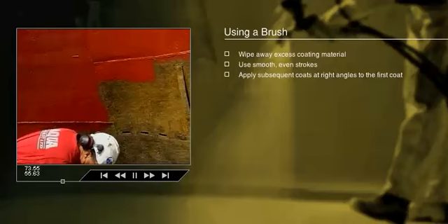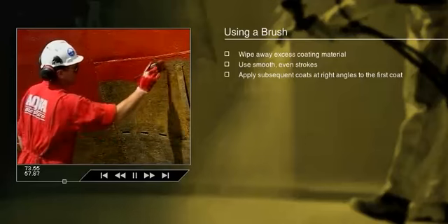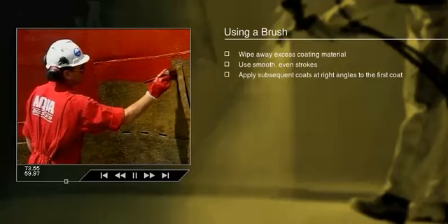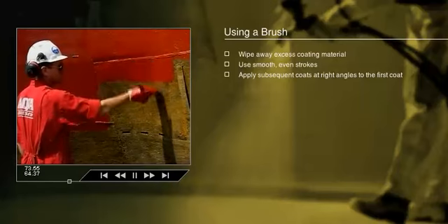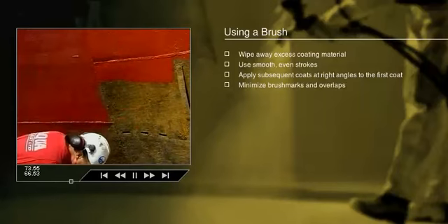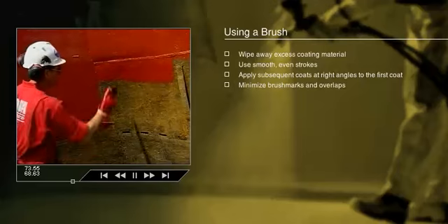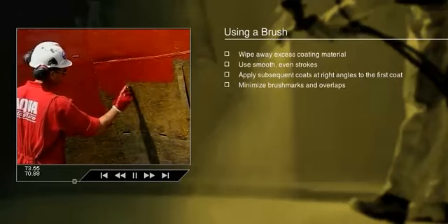The applicator should maintain a wet edge and brush the coating out from a newly coated area towards the previous wet edge. This practice minimizes the visual appearance of brush marks and overlapped work areas.